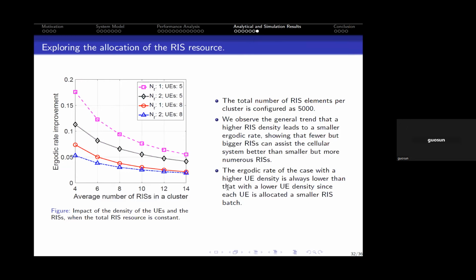Okay, and then we explore some ways to allocate the RIS resources. One thing to specify, one disadvantage of RIS is you cannot reuse the RIS resources, because if you do analog beamforming, the phase shifts of these elements, once configured, cannot be shared with others, unlike modulation technology. So perhaps the takeaway here is we should use one huge RIS and then serve few users.